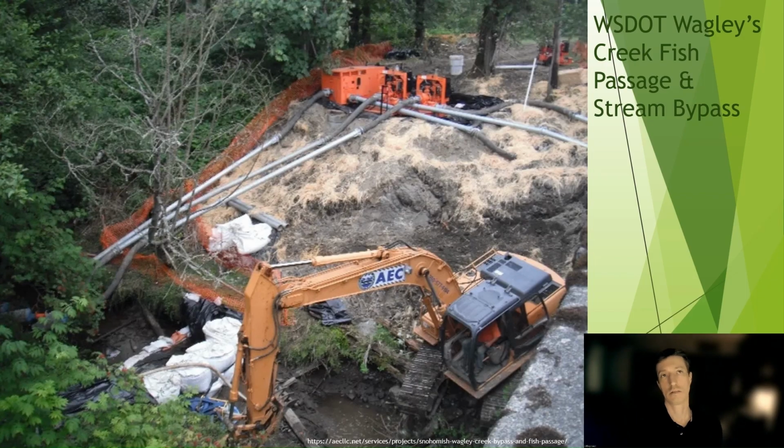Another thing to consider is developing a stream bypass while the construction is taking place. In one of WSDOT's barrier removal projects located in Snohomish, shown here, a very involved effort was required that included constructing a temporary access road along with pumps and temporary damming required for that bypass.